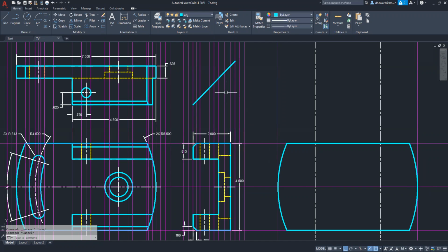To make a 17-degree construction line and a negative 17-degree construction line, which is what I'm going to do. So I'm going to go to my construction layer and I'm going to type XL, enter, A, enter, and then negative 17. And I'm going to run it through this point right here because that's its center. That was given to us. And then I'm going to do the opposite and say XL, enter, A, enter, positive 17, and click here. So that is the swing of the arc. There it is, right there.